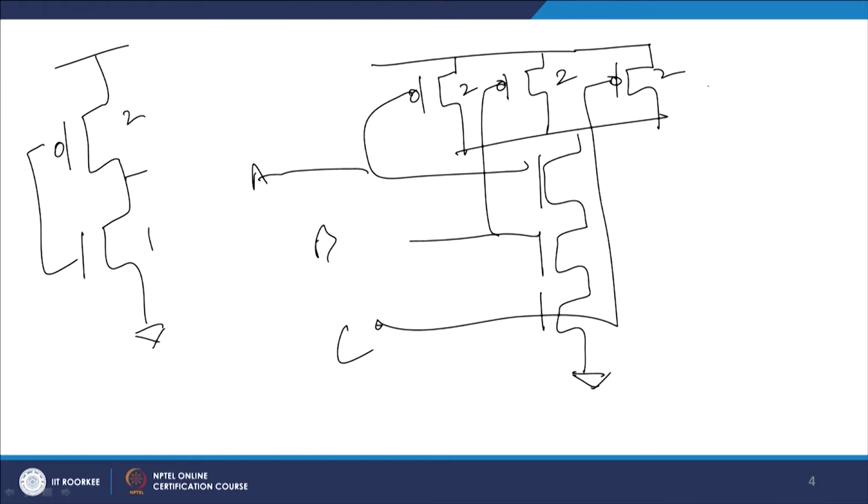then of course, as I discussed with you, the PMOSs will all be 2, has to be all 2, right, because you require only one of the PMOSs to switch on for a low to high transition. So, this is my output here. I only want one of the PMOSs to switch on to ensure that you have a low to high transition in the output, whereas I want all my NMOSs to switch on to have a high to low transition.